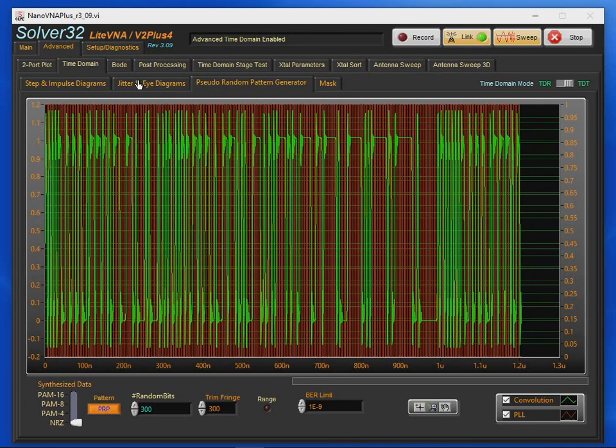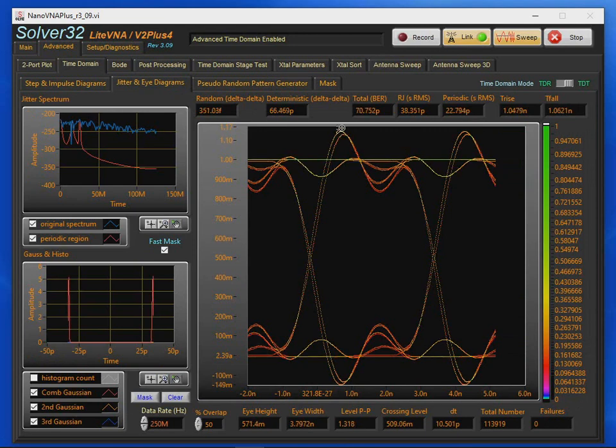And now let's go ahead and display the eye diagram. And there you have it. So roughly 1.05, call it a nanosecond rise, maybe 1.06 nanosecond fall. Again, that pulser on the scope I think is an open drain and it's not symmetrical. The output of this is symmetrical. So even though it's kind of a quasi square wave at this frequency, because it is symmetrical, we do get the same rise and fall time. And again, the signal that I'm synthesizing, of course, is going to be a perfect square wave.